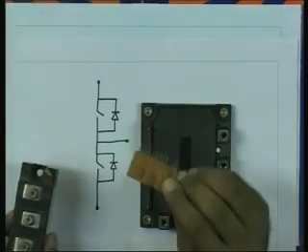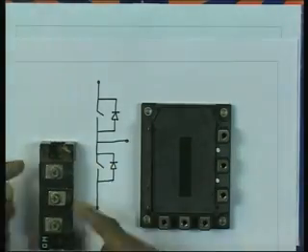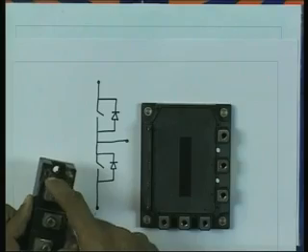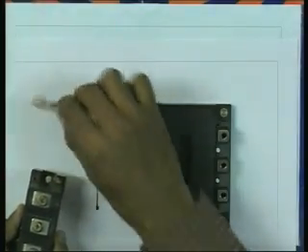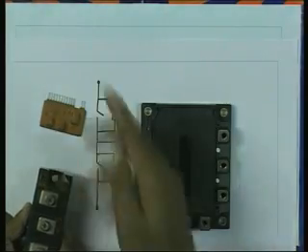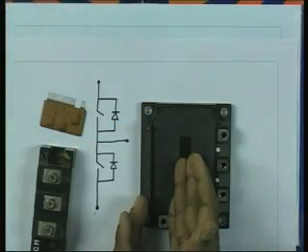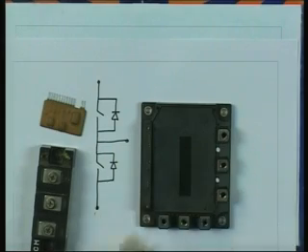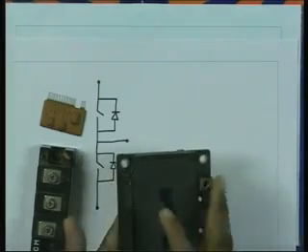I said you require a separate dedicated supply, or you need to have a separate driver circuit to supply the required gate drive for this transistor. So this is the dedicated chip that is used to drive this. You can design your own circuit using various discrete components, transistors, small resistors, and op amps. Whereas this circuit has the driver circuit built in, what is known as the intelligent power module.